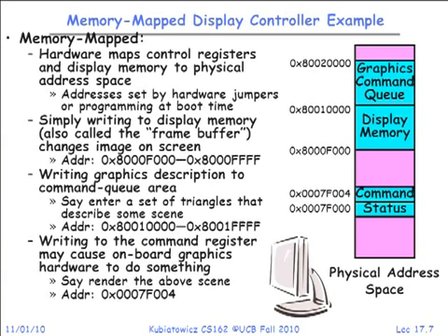So let's back up for a second. The answer is you never actually write to memory. A CPU writes to an address that's been mapped to the hardware, and that address comes off the memory bus, and then rather than going to DRAM, the bus adapters say, oh, this is an address that I should recognize. The write goes directly to the device. It doesn't actually ever go to memory. So it's like a trigger and data all in one, because the act of writing causes something to go to the device and causes the device to wake up and do something. So that's a good question.